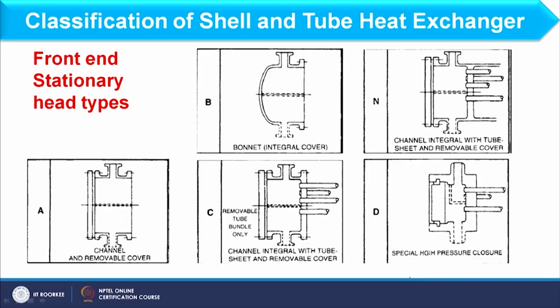So here I am considering some stationary heads of front and rear side. So you can consider the front head. So here we have a channel and removable cover. So here you can simply remove this cover, which we can consider as the cover of the flange, okay, because it is attached using a flange, okay.